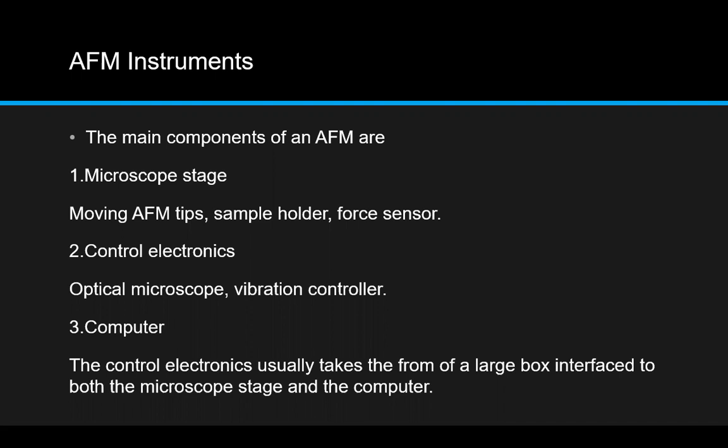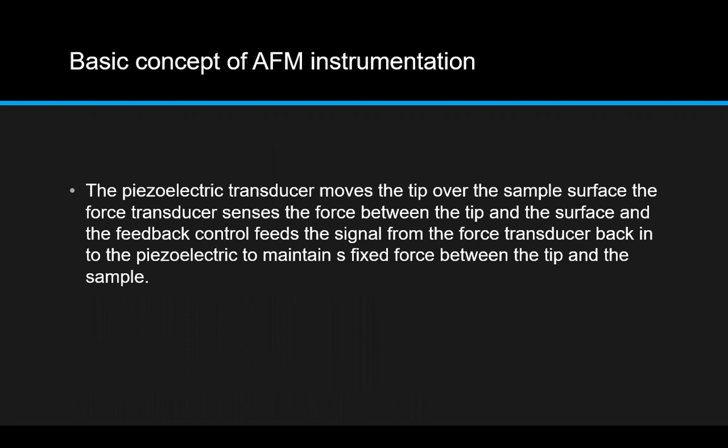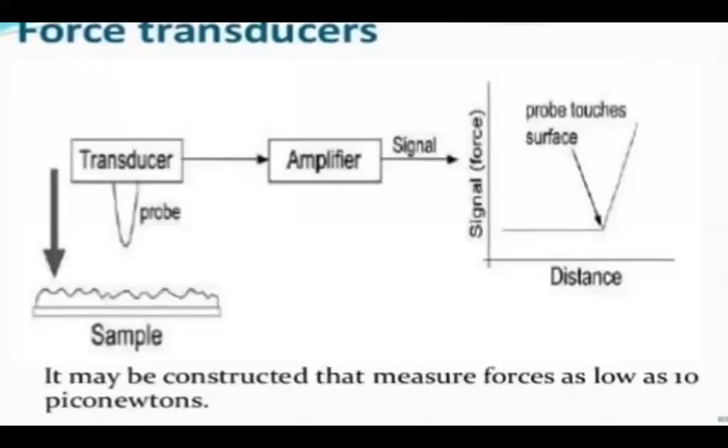The basic concept of atomic force microscopy: the piezoelectric transducer moves the tip over the sample surface. The force transducer senses the force between the tip and the surface, and the feedback control feeds the signal from the force transducer back to the piezoelectric to maintain a fixed force between the tip and the sample. The diagram shows the transducer and probe on the sample, with an amplifier also connected, and the signal shown by the graph.